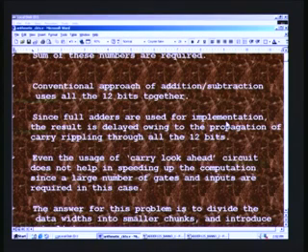That is the reason why the whole adding process is quite delayed. The more the number of bits, the more the delay, and therefore the processing speed goes down. You can improve the speed by bifurcating this data to lesser values, say half of that 12, maybe 6 or 7 bits. Even the usage of a carry look ahead circuit does not help in speeding up the computation, since a large number of gates and inputs are required in this case.